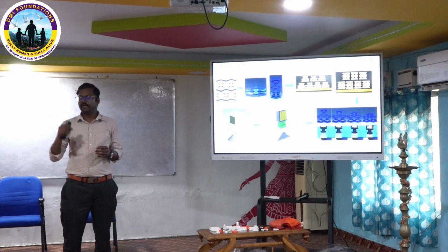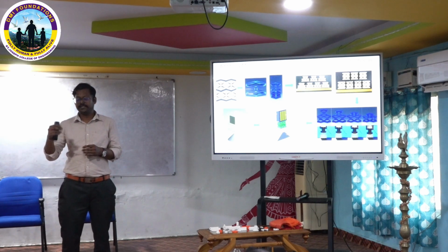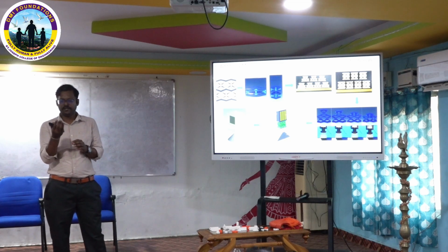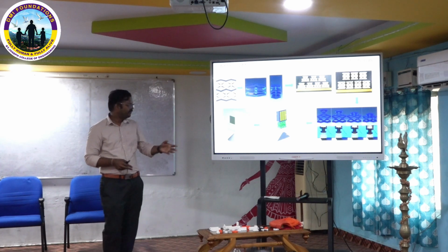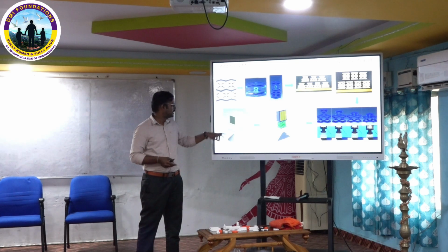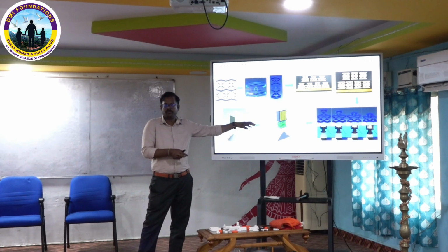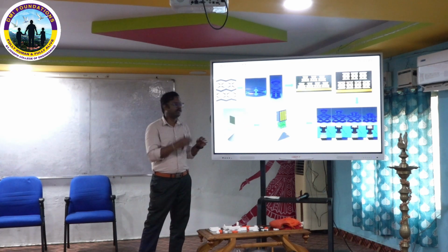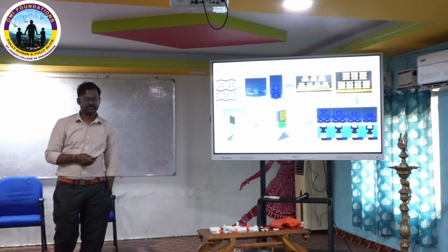While running the bike or car, a stone on the road gets compressed by the tire and impacts the battery cover. That impact can blast the battery. Due to that, 2 to 3 accidents have already happened. You can search online also. So to rectify that, we incorporate this lattice structure below the battery cover. If there is any impact, it can be absorbed by the lattice and will not transfer to the battery case. So it will reduce the accident scenario. That is the main motto.